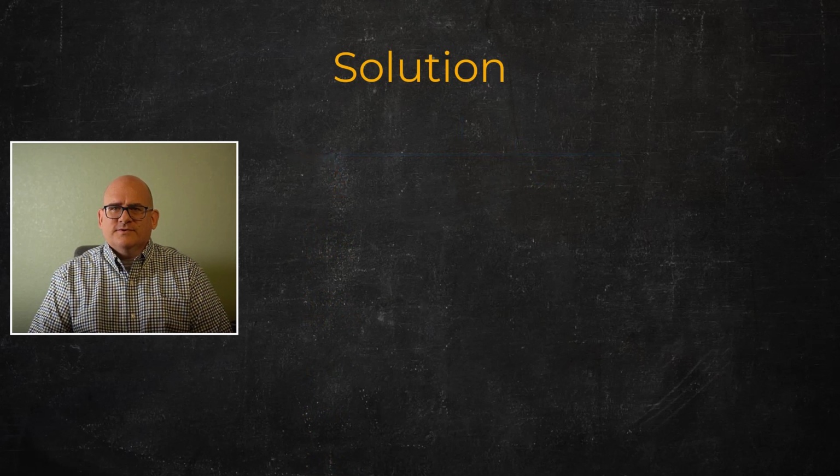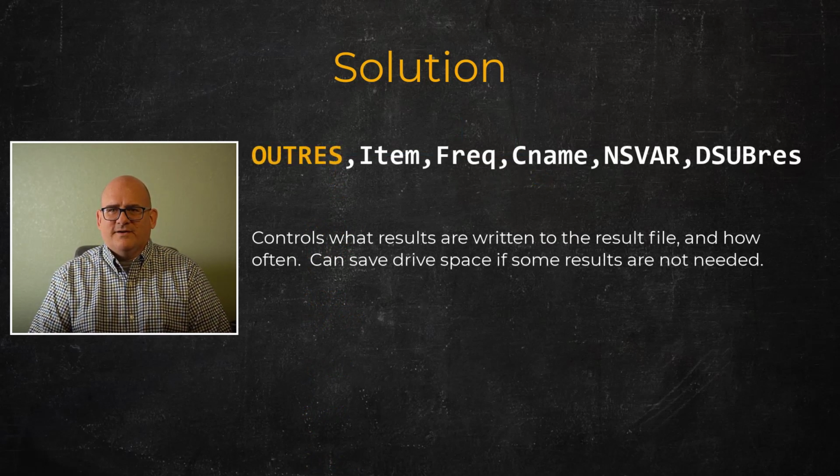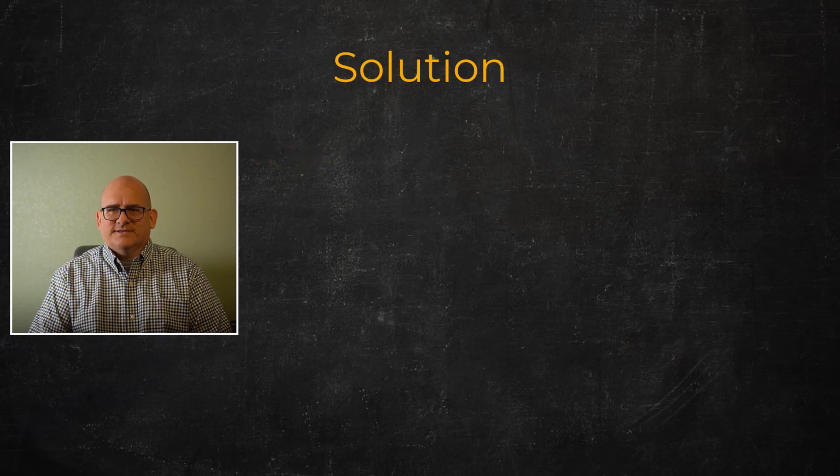During the solution, result items like stress, strain, displacements, and the like are saved to the result file. The OUTRES command can be used to define the frequency at which user-specified results are written to the result file. This concludes the lesson on loads and boundary conditions, so let's move on to a workshop example.